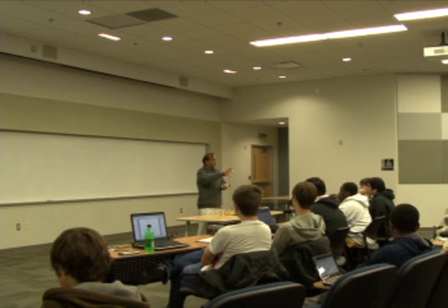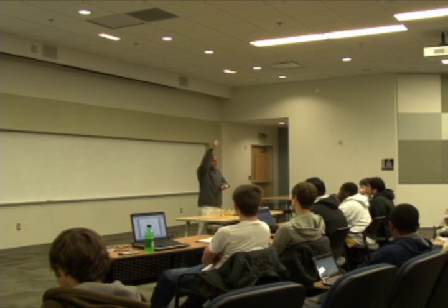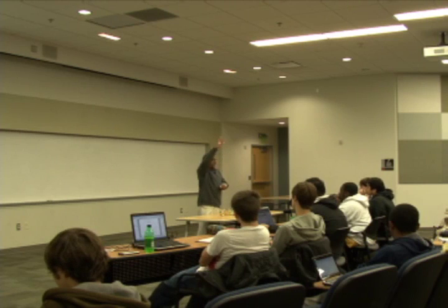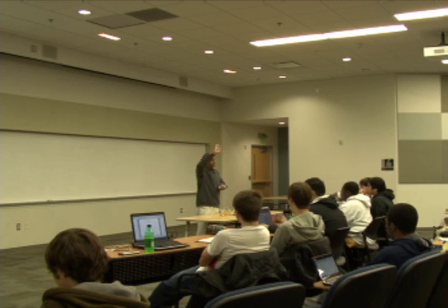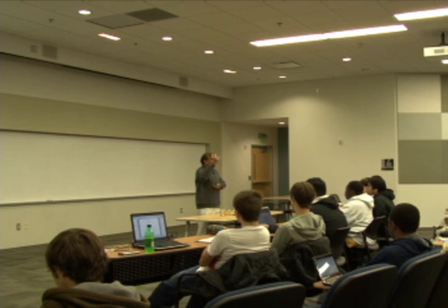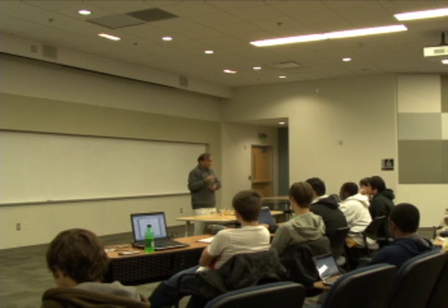One half is when Z is 0, and that's the normal sequence of instructions. And Z equal to 1 is going to take you to a different portion of the ROM, and all of those portions are irrelevant to us, right? There are only a few locations that are relevant to us when we explicitly set the Z-bit to 1 in our data path. Is that idea clear?